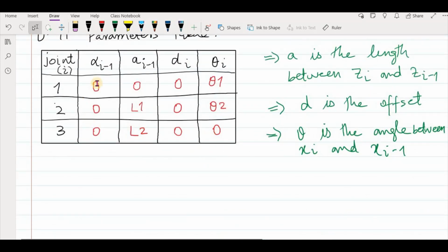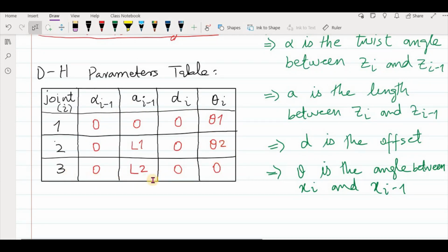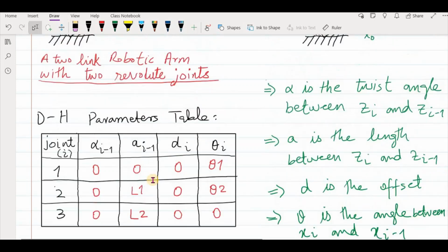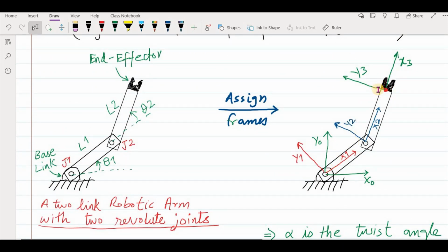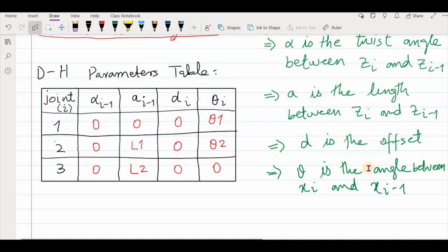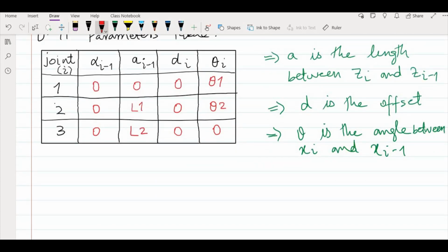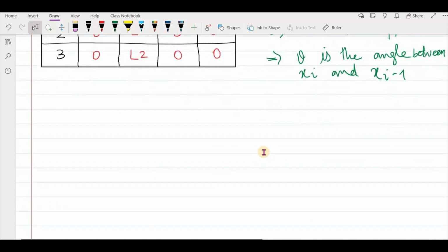So once you have all these parameters for your DH table, now you can use the transformation matrix, which was designed specifically for the DH convention, to find the transform between the links, and finally the transform between your reference frame 3 and the reference frame 0. Okay, so according to the DH convention, what was the transform? It's mentioned in the previous slide, but this time we show a transform which is a little bit different.